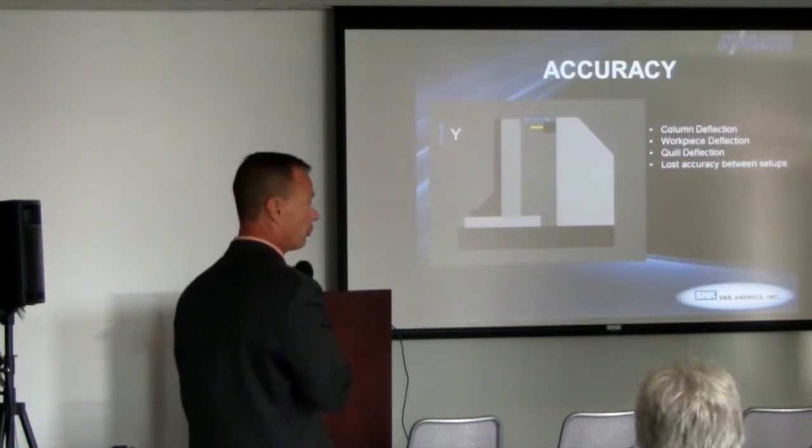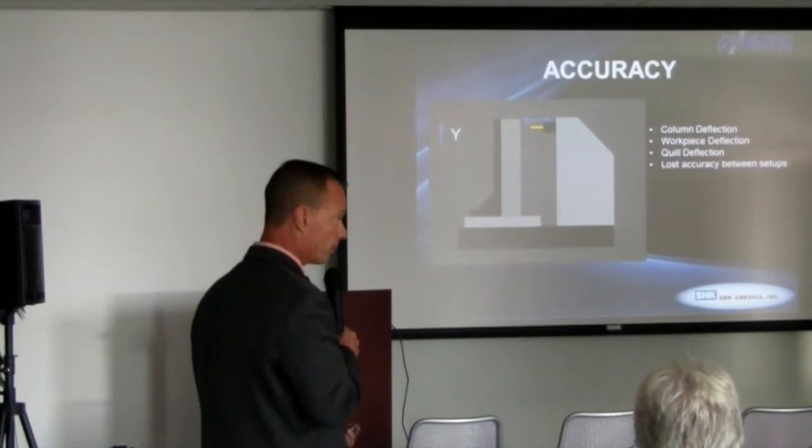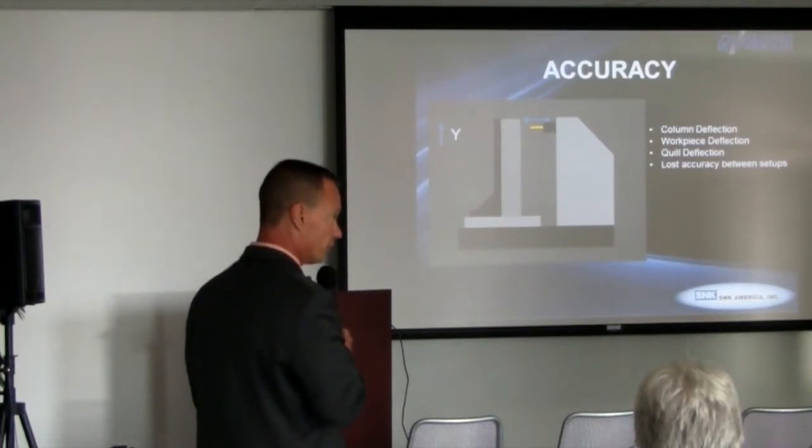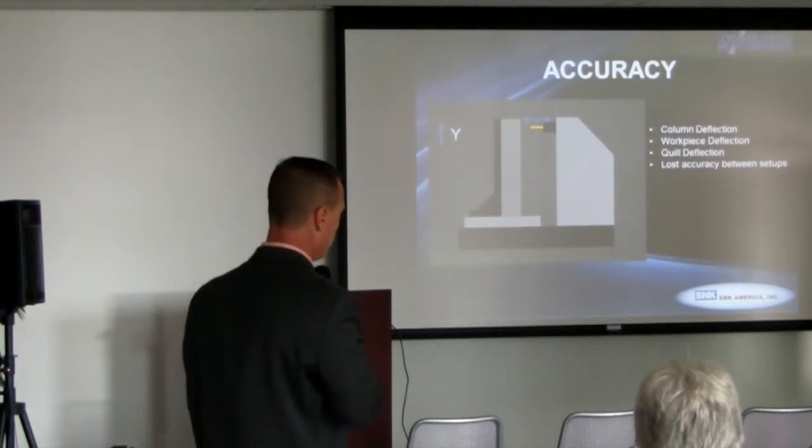So the column will start to push back. The harder you push on the part, the workpiece setup, the farther you are off the table, you start losing cutting capability and also accuracy.